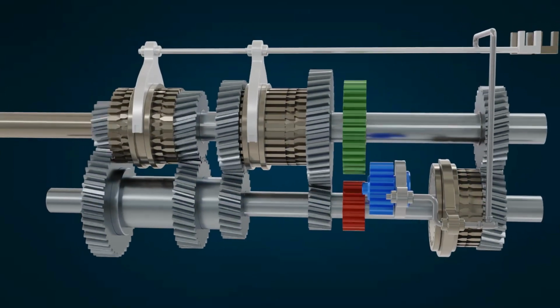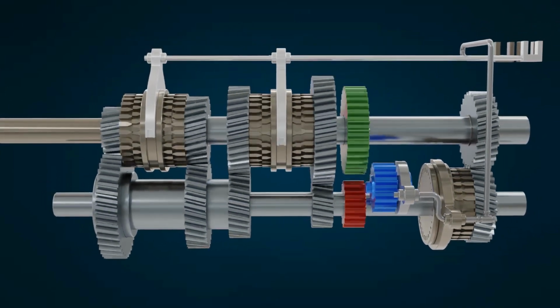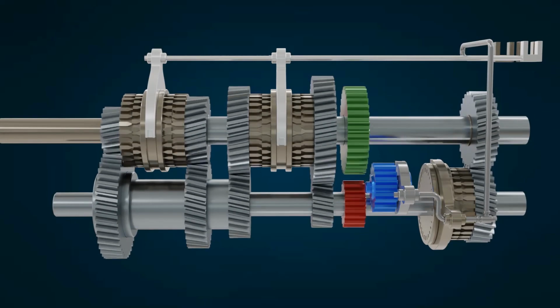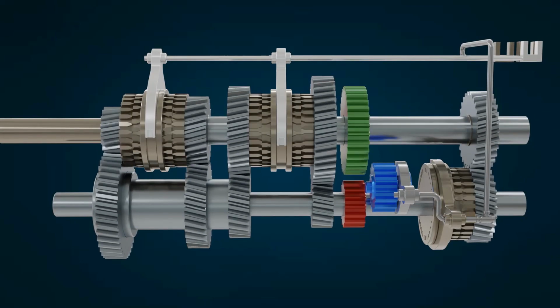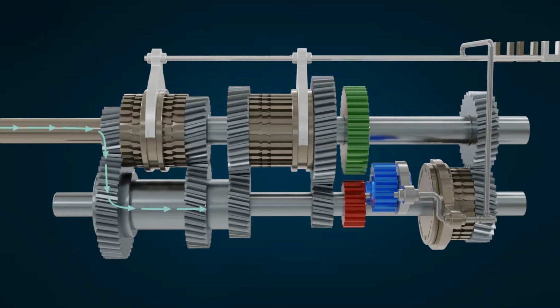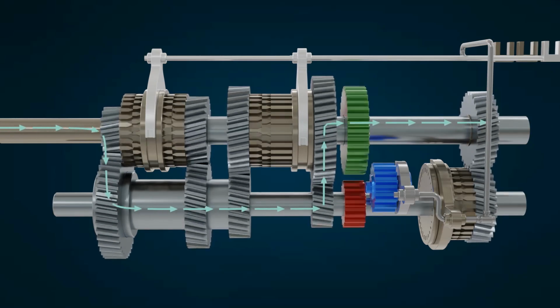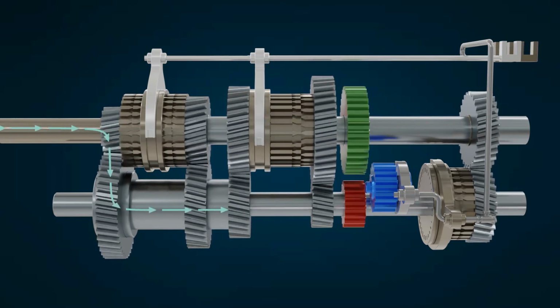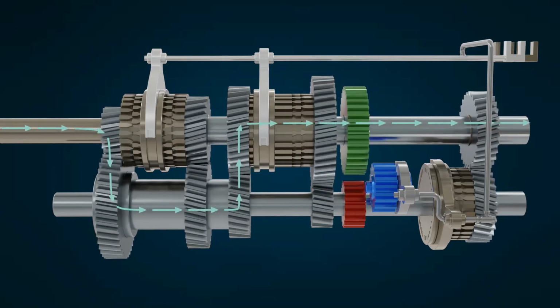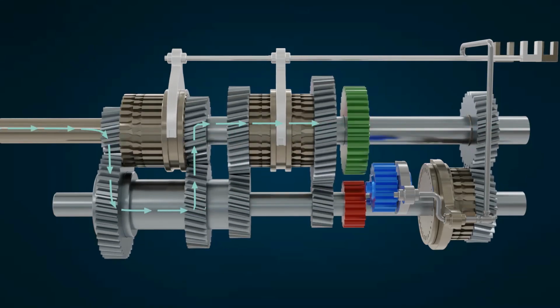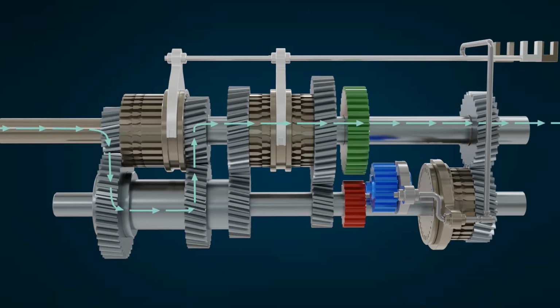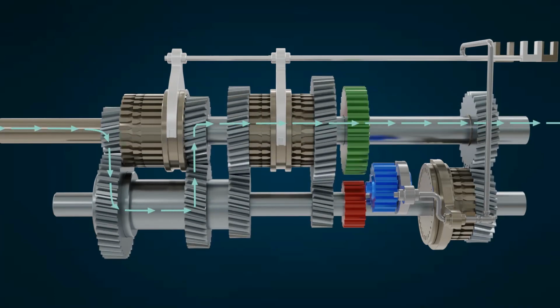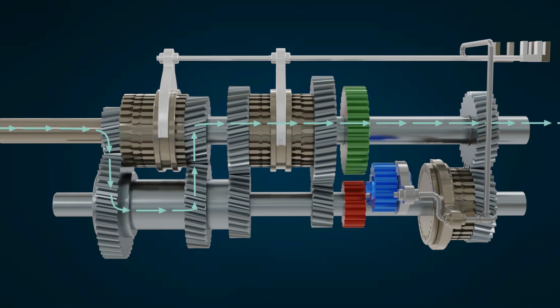Gears are used to change torque. Gear ratios of greater than 1/1 are reductions in speed and gains in torque. Gear ratios of exactly 1/1 are direct drives with no change in torque or speed.